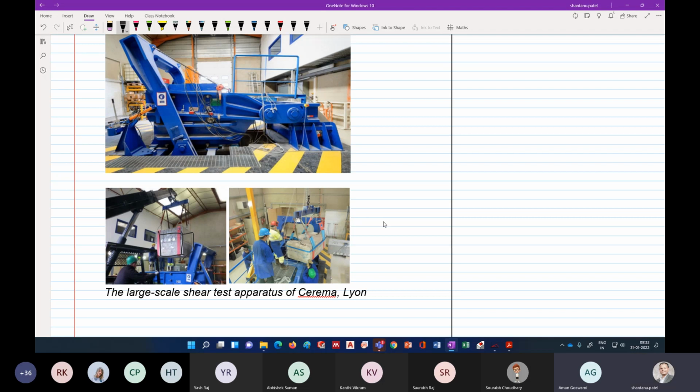Okay, so let's say you are designing some dam, right? A big dam, let's say. And this dam is resting on a rock foundation. So it's very critical, right? If the water pressure is too high, and the foundation is not good enough to take care of the shear load, then the whole thing will slide and it will kill thousands of people, right? So you need to do a good, high quality investigation in these kinds of cases. Okay, is this clear? Yes, sir.